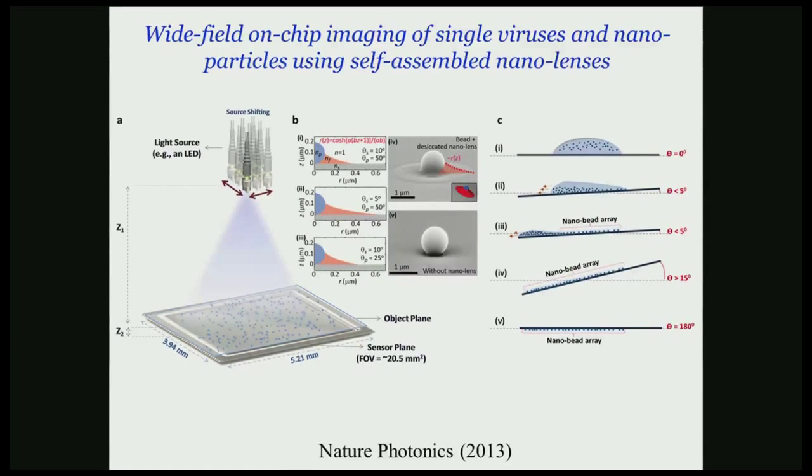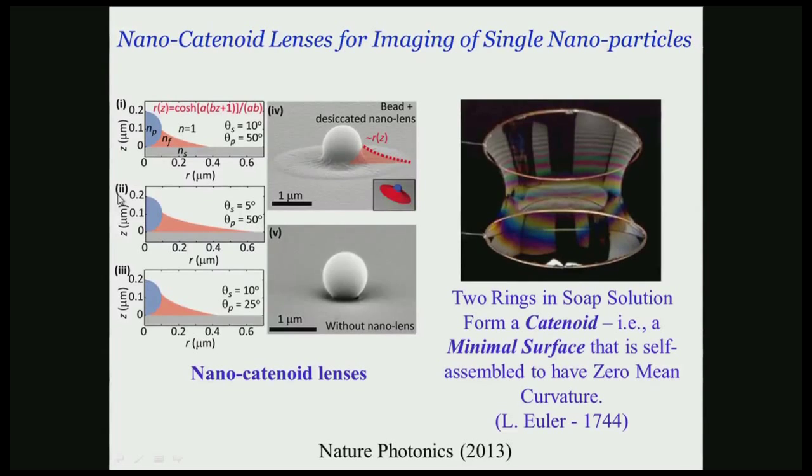So far, I've been focusing on resolution and methods to improve the resolution beyond the pixelation limit, beyond the undersampling limit, dictated by the CMOS hardware. But there's another element to microscopy or sensing, and that is looking at sub-micron, sub-wavelength particles or objects that do not scatter light much. For that, especially looking at sub-50 nanometer particles or sub-100 nanometer particles, we've created an interface which uses self-assembly.